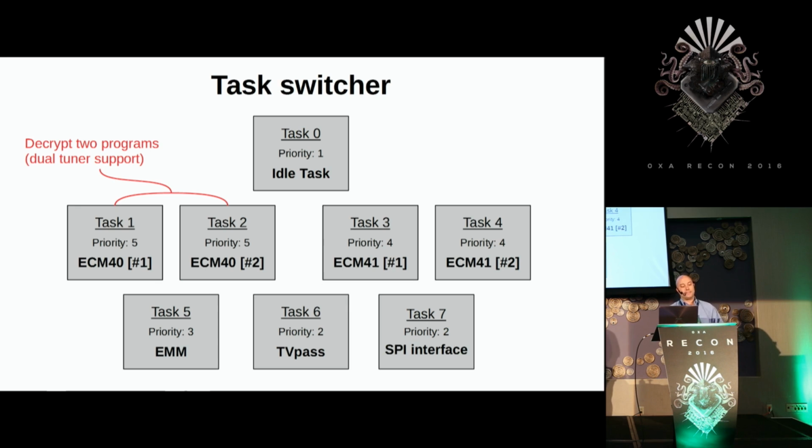One of the first things I saw in the disassembly was that there were 2 operating modes. During startup, values in RAM are checked, and if the ACP has not been initialized, then it enters a personalization mode. This is used during manufacturing to assign the unit address and the seed keys. In normal conditions, after the set-top box has left the factory, this personalization software is bypassed, and the ACP always runs its main application. The next thing I found was that the application was not a really simple program.